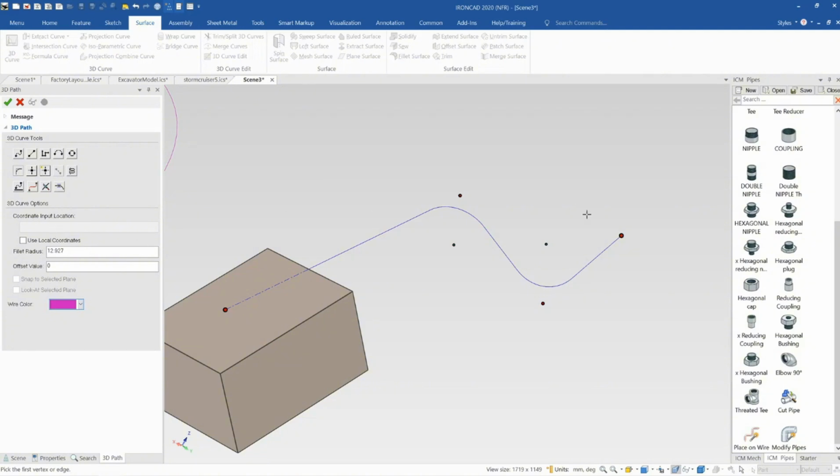Now you might be wondering how you edit these fillets. If we deselect the fillet tool, we can click on this fillet and click on this. Oh, not that point actually. Click on this point, the center point, I think, of the fillet. We can click on that and we can drag this approximately. But if you'd like to, you can also right-click on the fillet and select Edit Radius, and then you can type in a specific radius. So we can say, okay, that should be 10. Same here. We can click on this, right-click, select Edit Radius, and change this to be exactly 20. That's the fillet option there.